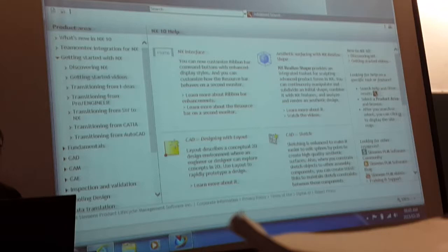Today, we're going to proceed with a 3-step process. So we've done step 1, creating the part file. Right. Step 2 is to create this finite element model where the mesh is basically generated and our material properties are associated. Right, so I right click on our part file name and I say new FEM.